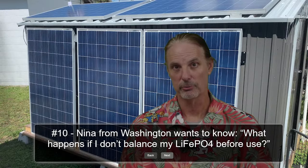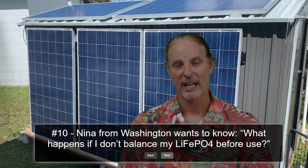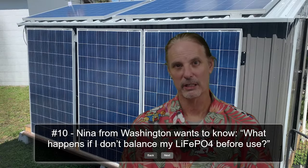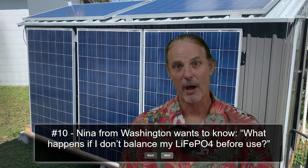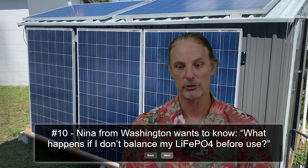That could cause you some serious problems. And make sure, of course, you have proper fusing and all of that, and double check your specs from the manufacturer to make sure you're not breaking any of their input output rules as far as how much amps it can take and how much it can charge and how much it can discharge.